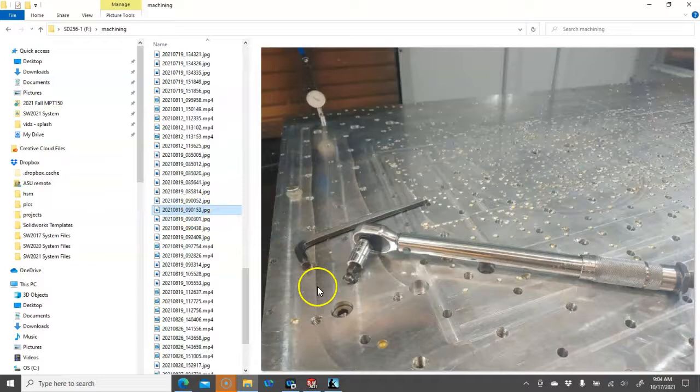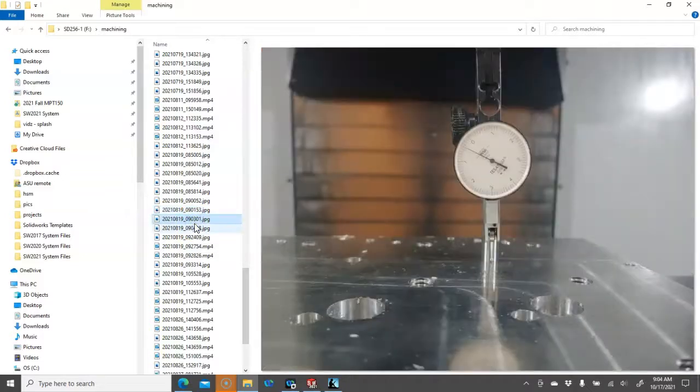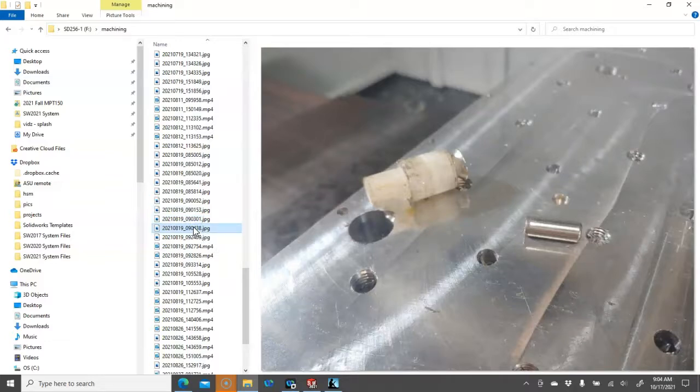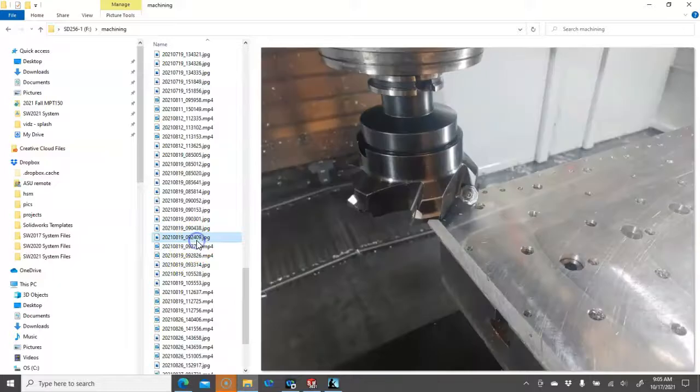So these get snugged with a standard Allen wrench, but then so that everything is consistent, so that there's minimal amount of warpage in the torquing of the socketed cap screws, we'll use a torque wrench and torque them to about 60 to 70 foot-pounds. I don't remember what I use. It doesn't have to be extremely tight, but I want them consistent. And a couple more pictures, and there's the little tool and the dowel pins. So this has a 3-inch spacing of dowel pin holes and 1/2-13 tapped holes to perform the mounting.